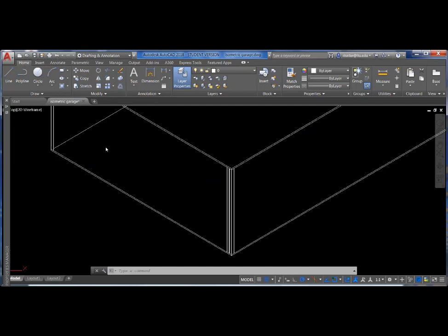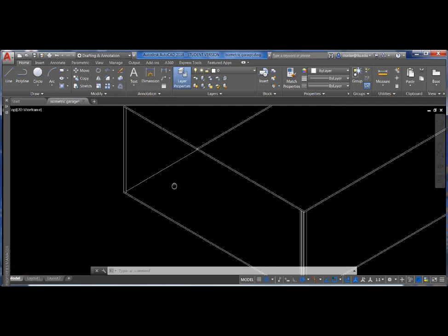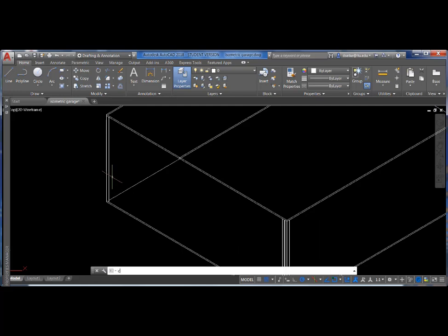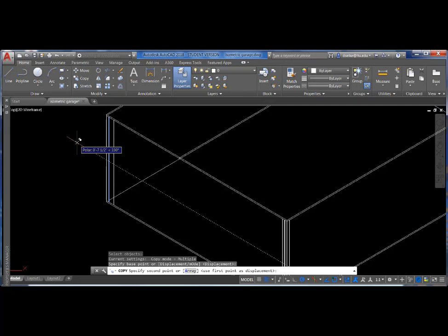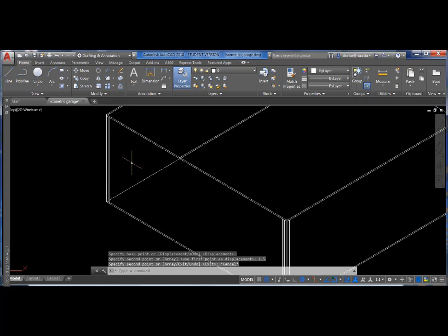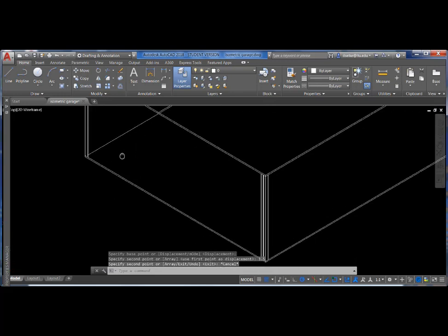Moving back to the left corner, we are going to copy this line over 1.5 inches to represent the studs. I set my polar angle at 330 and type in 1.5, 1.5 inch over. Now we're able to array these lines down 16 inches apart. Let's do that.